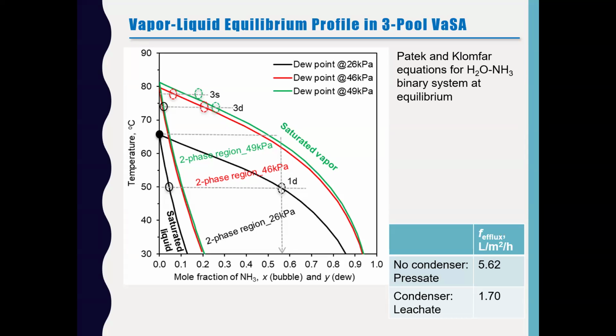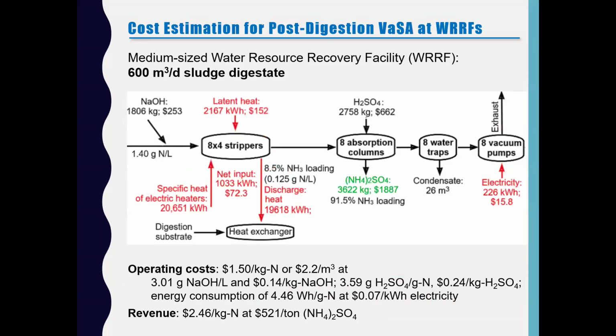Next stage, we are going to modify the demister and ideally reduce the demister temperature to 65, and hope the vapor will have more ammonia to separate. So that's our next stage. It's more complicated to find the optimal condition for full-scale design.